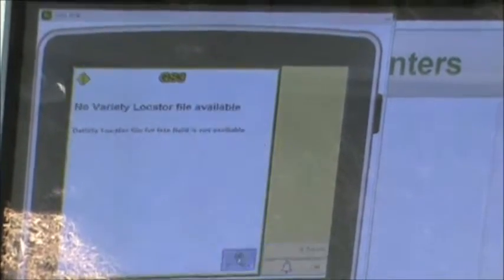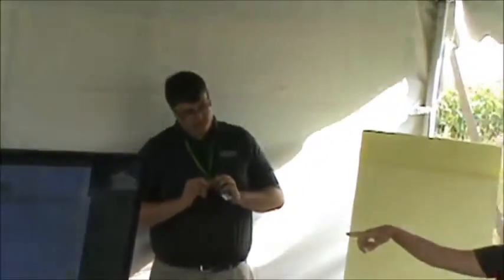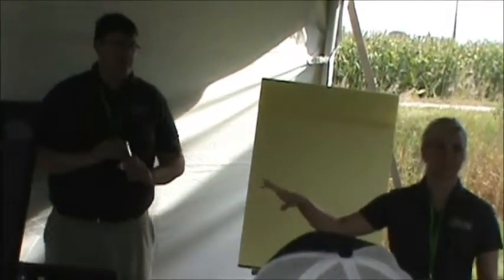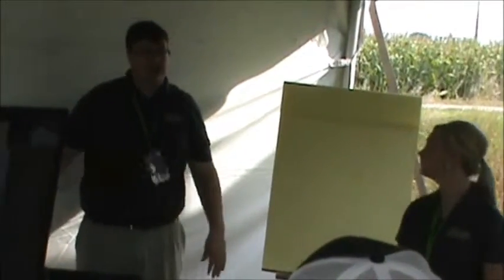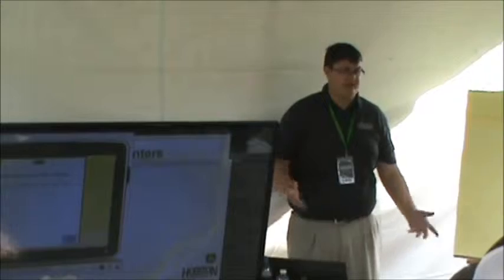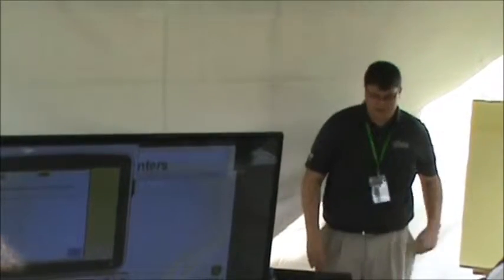If you guys are running a 2630, make sure you have a clean flash drive. Yep. For sure, because if it wants to import other things, that's going to mess it up. So just make sure that your flash drive is dedicated to this and only this. You want to make sure if you're bringing something in that it's the only thing on the flash drive. It prevents errors or somebody making a user mistake or something like that.